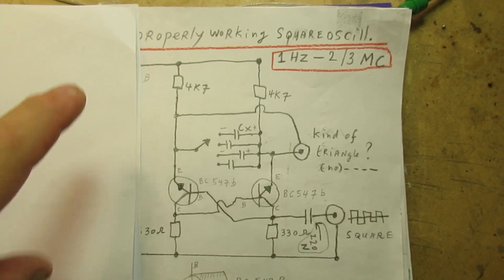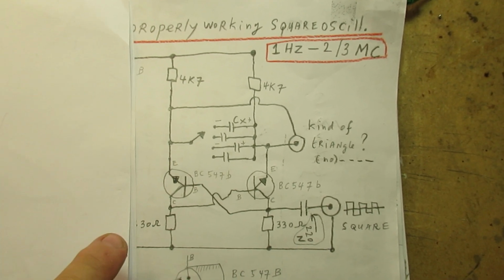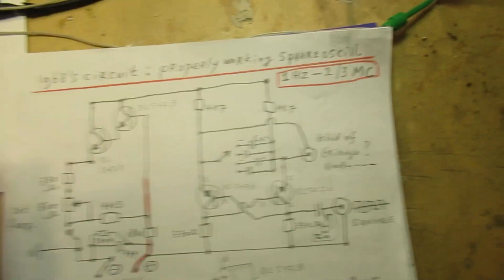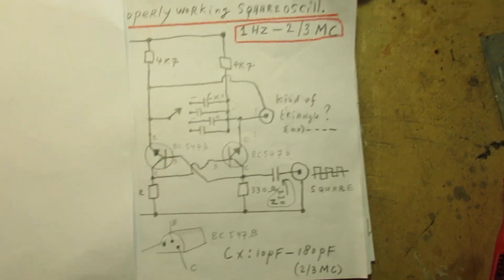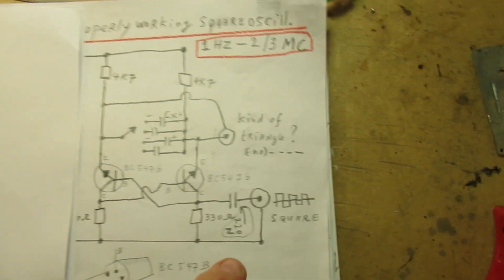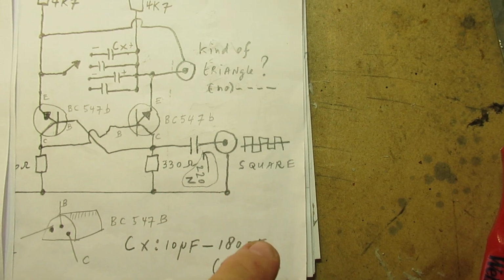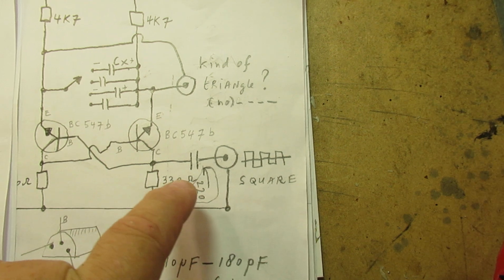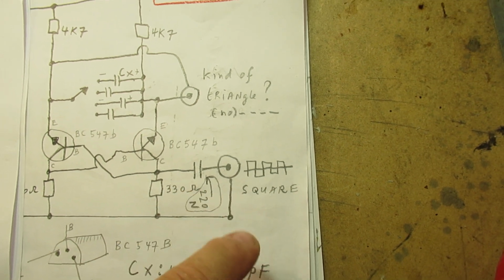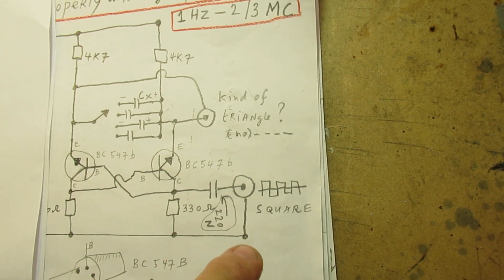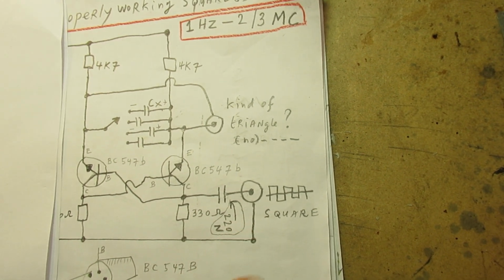Important to tell that when you want to make this circuit both in its original way, thus this, and now in another way, you need of course here a kind of buffer stage, because when you load the multivibrator with some resistance, the waveform will change, many other strange things are going to happen, etc.